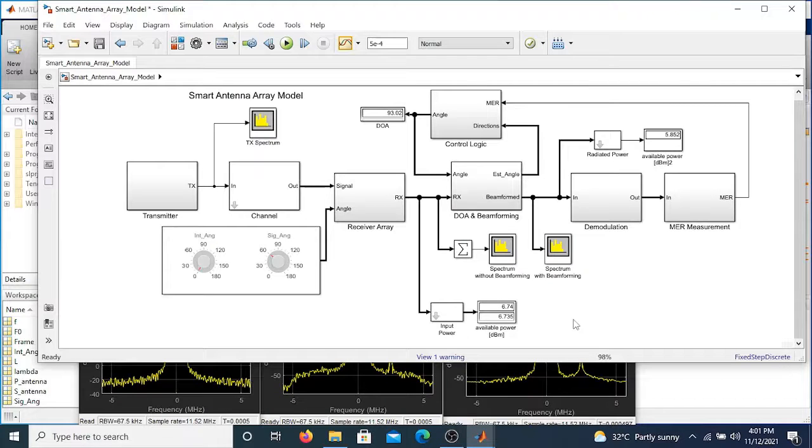With the latest results, you can observe that the radiated power has improved as a result of the increased spacing between the antenna elements, and the efficiency is around 86%, which can still be further improved by increasing the spacing to, let's say, 1.95 lambda.